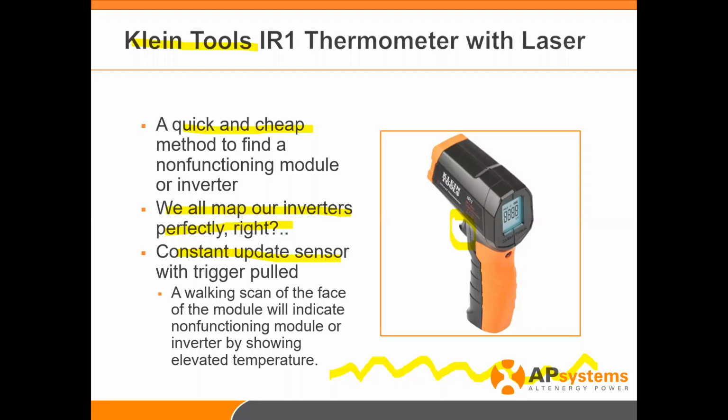You found the one that is not operating. Guarantee there is no current. So the nice thing about troubleshooting modules and troubleshooting where inverters are located is the module that has the higher temperature is the one that is not working. It has to be significantly higher.